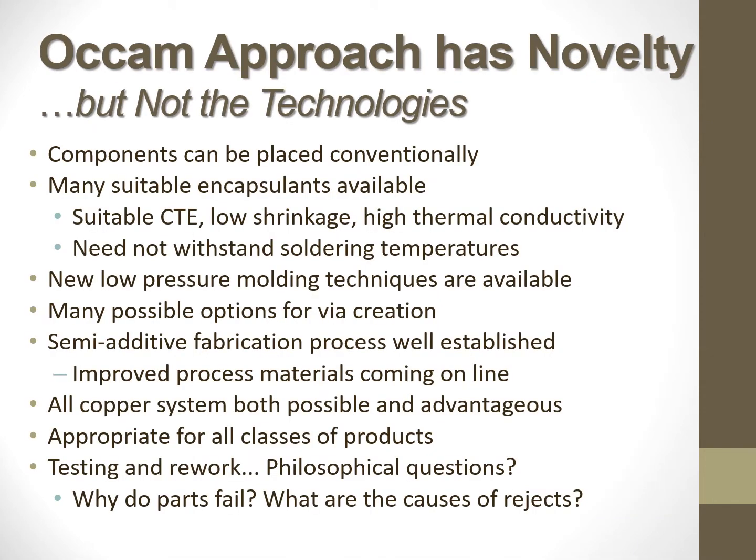So the Occam approach has some novelty, but not the technology. The components can be placed conventionally. There's lots of suitable encapsulations in terms of coefficients of thermal expansion, shrinkage, conductivity. There's molding technologies that are available, lots of methods for being able to make the via creations. Semi-additive process fabrication is well established. Lots of new materials are coming online. Potential for building an all-copper system, and it's appropriate for all classes of products.